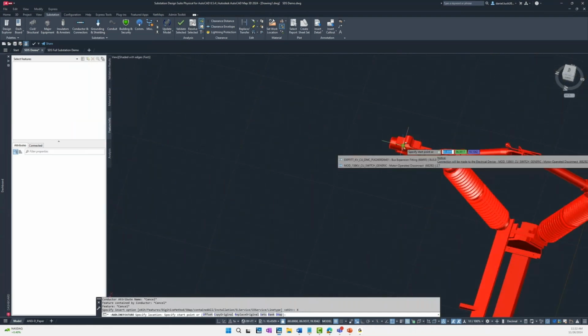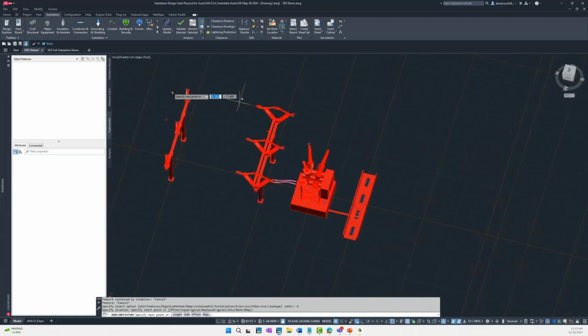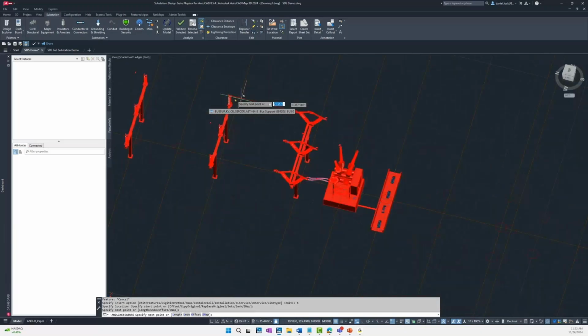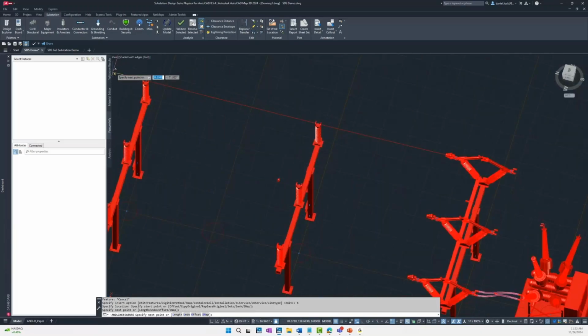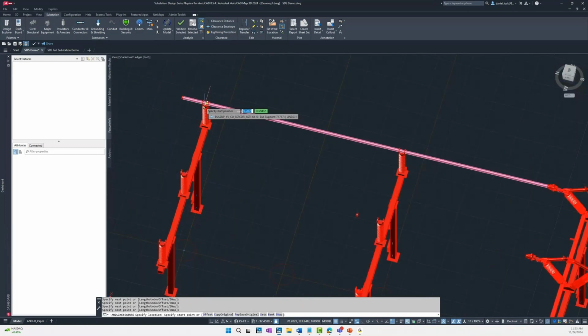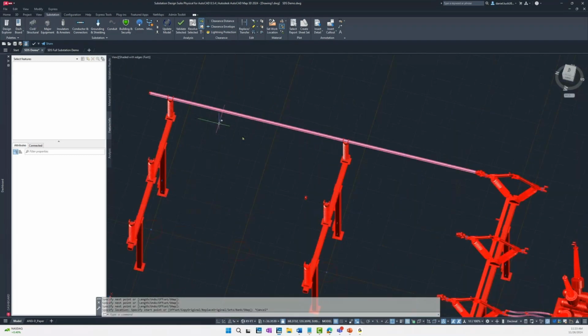We'll select to the port on this expansion fitting. And then we'll connect to every single piece of bus along the way to keep that connectivity and containment information in place as well. We'll digitize the bus section, and there we go. Now we have our section of bus.